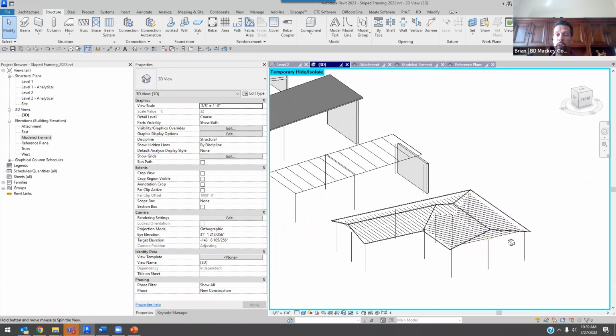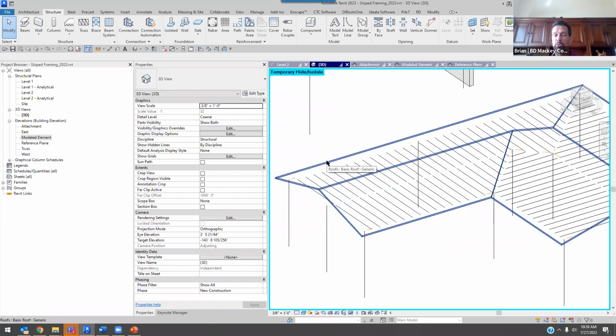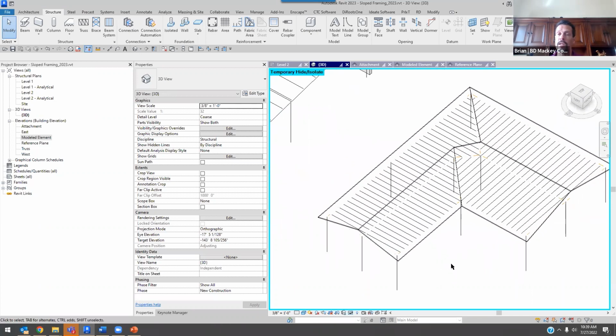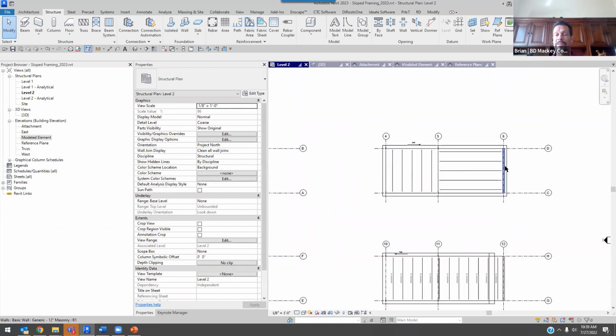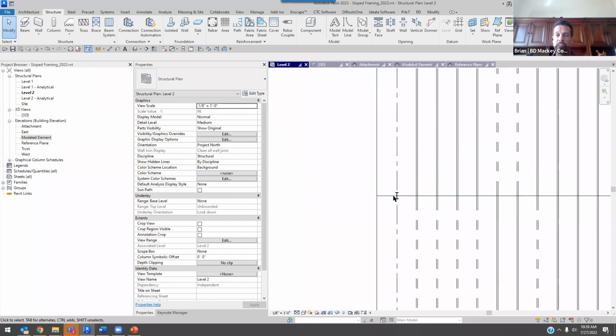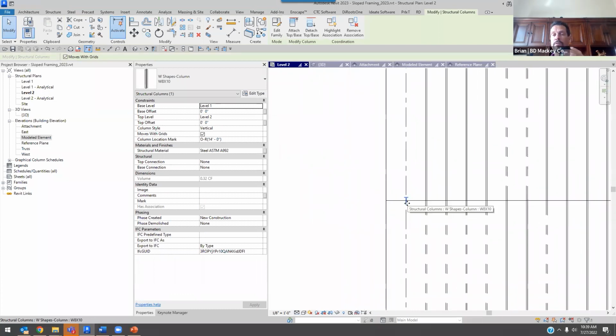So in my real projects, I have specific views where all I'm seeing is the architectural roof. I've got filters to turn things on and off, and then I can just keep reattaching all of my columns. Now, in this case, you will start to see it's looking more like a residential type roof. I'm going to get out of my coarse level and go into a medium level of detail. You are going to see that I did put a column, and I just threw wide flanges in here. It could be anything you want, but I did throw a column everywhere I know there's going to need to be a slope.